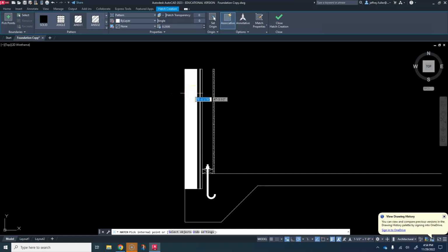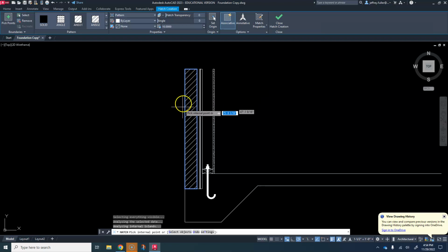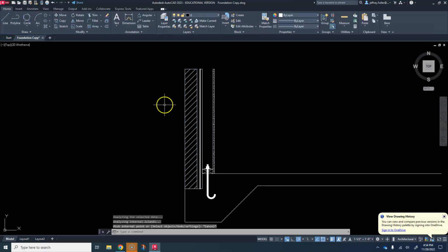All right, I'm going to place it right here in my wall. Now, of course, you can see that it has retained the scale that I set it for the gypsum wallboard, which is going to be too small of a scale for my brick. So I'm going to set the scale for my brick to something like 10. Okay, that's pretty good. That's what brick should look like. That is the symbol for brick. It doesn't look like actual bricks, but that's what we use.